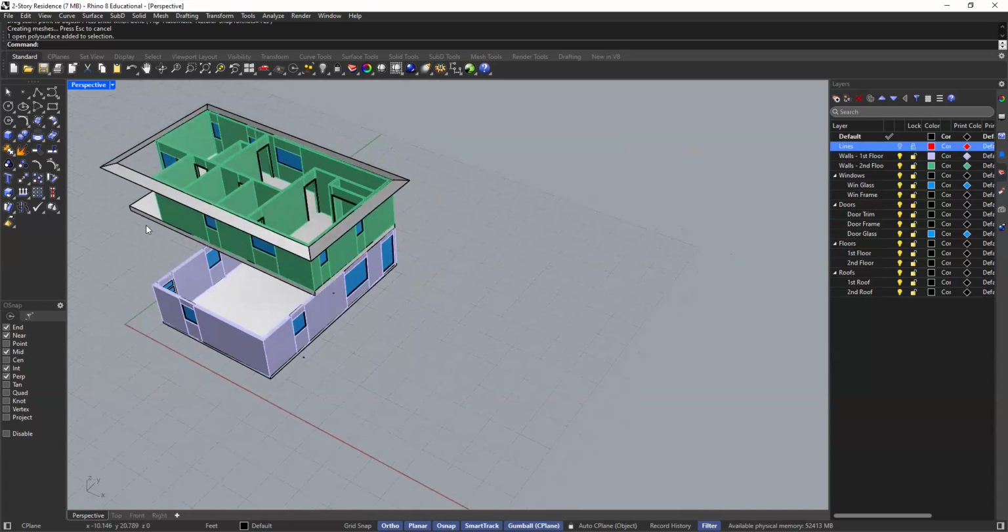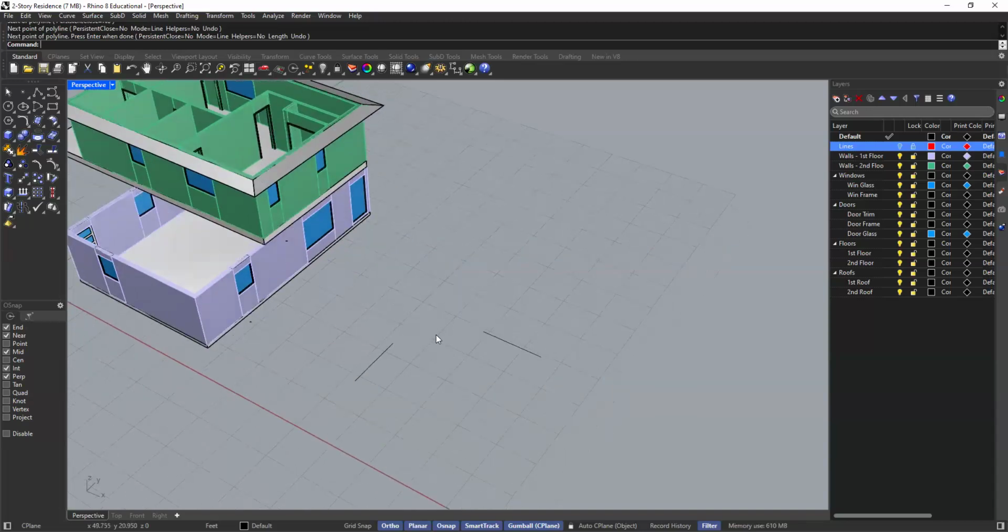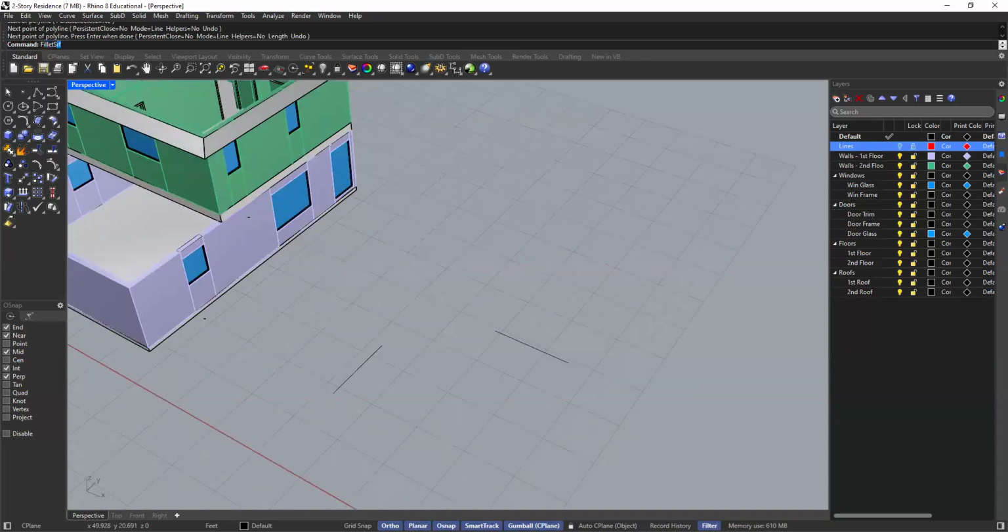Now there's a 2D command called fillet that we use whenever we want to round off. And I may have covered this one. Whenever we want to round off, not fillet surface, just fillet, the corner wherever two lines meet. So if I click there and then click there, right, it gives me this 2-foot radius because I entered 2 feet.